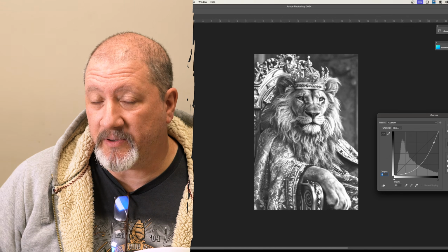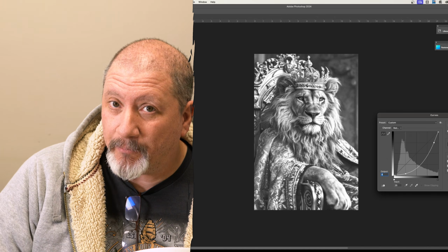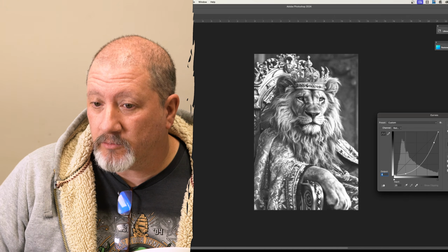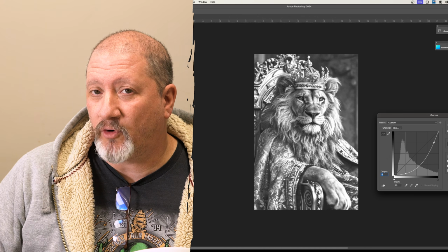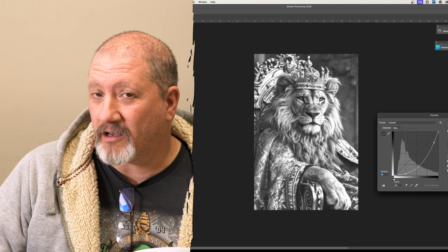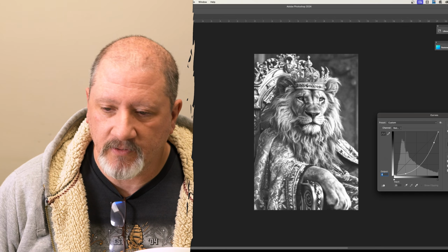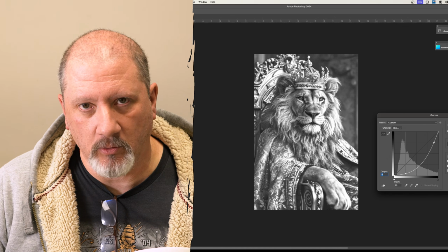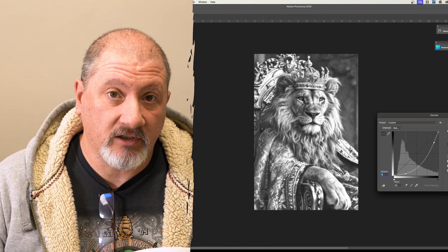That's how much compensation we are making so that when that 4% dot hits fabric, it creates a little bit of physical spread, that physical dot gain, and also that optical dot gain for how bright that white dot looks on the fabric versus contrast. So it looks like shadows. That's the foundation that you are going to be working with to create a good looking transfer.